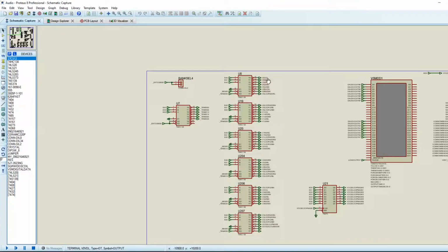Now, all of these registers map to the voice-specific registers, and most of these are 8-bit matches. Okay, we're not using RAM. We want to vastly simplify the access to the sample register memory, so using a large amount of latches makes sense rather than trying to figure out all of the memory access logic. So this is the address decoding logic here.